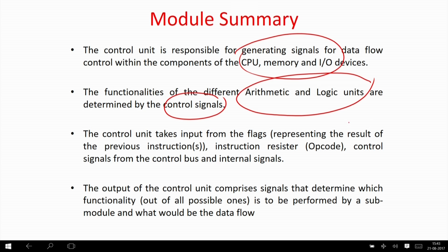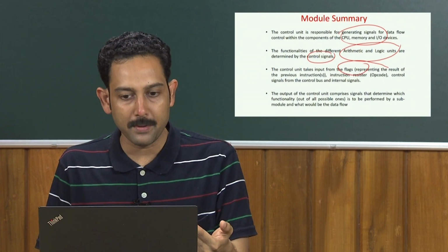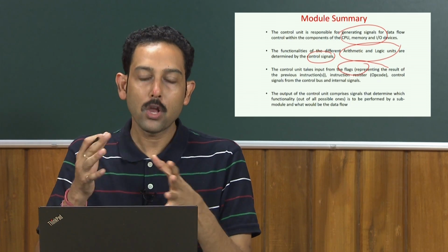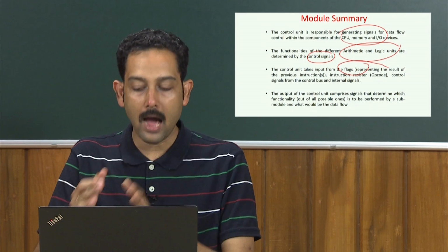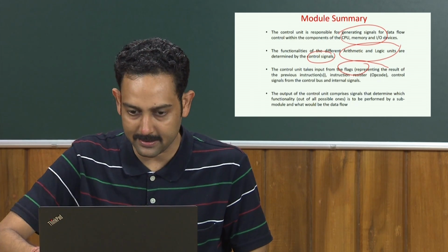For example, flags are set and reset, and they generate some control signals. How will those control signals be utilized, and how can you design a circuit which will read the control signals from the wire and modify the program counter? Now we will be looking at much more hardware-related issues than the superficial level of the last module. For example, the output of the control unit determines the signals which are sent to another functional module. Like if there is a peripheral device, it will interrupt your system, so what type of control signals will be generated? In a nutshell, we look at different types of control signals, how they are generated, and we look at them for different architectures like single bus, double bus and 3 bus architecture.